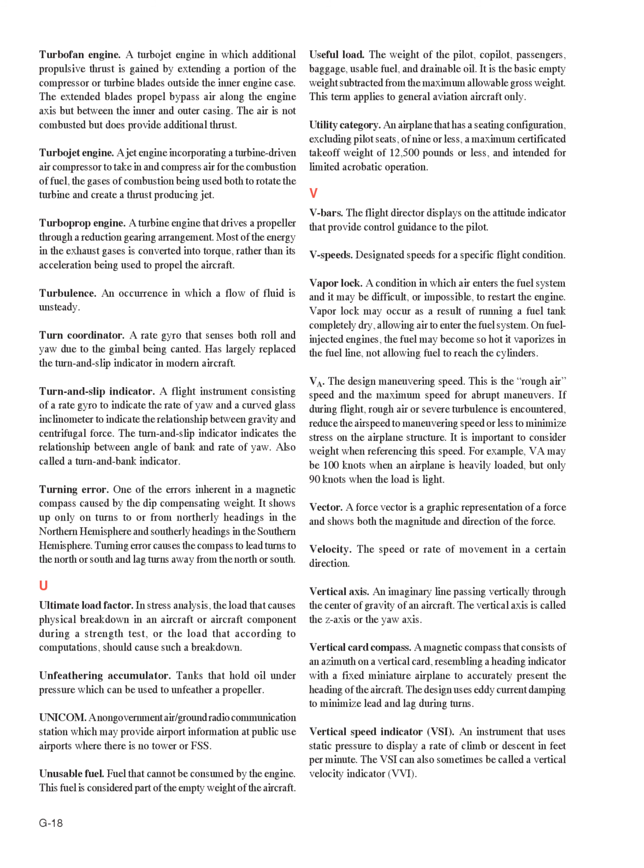Turning error. One of the errors inherent in a magnetic compass caused by the dip compensating weight. It shows up only on turns to or from northerly headings in the northern hemisphere and southerly headings in the southern hemisphere. Turning error causes the compass to lead turns to the north or south and lag turns away from the north or south. Ultimate load factor. In stress analysis, the load that causes physical breakdown in an aircraft or aircraft component during a strength test, or the load that according to computations, should cause such a breakdown.